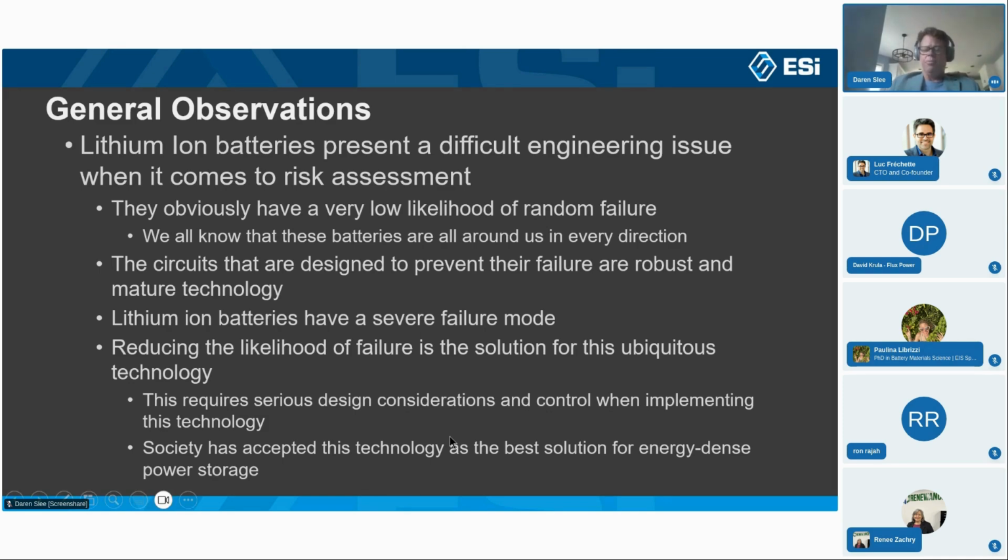So that's something that's not commonly considered when it comes to battery pack designs, in terms of making sure your pouch edges are nowhere near any kind of conductive metal in a product, because that conductive metal is always at battery negative, and that will make the aluminum pouch at battery negative, which will destroy the cell. So it may not be a severe failure mode, but it can be.